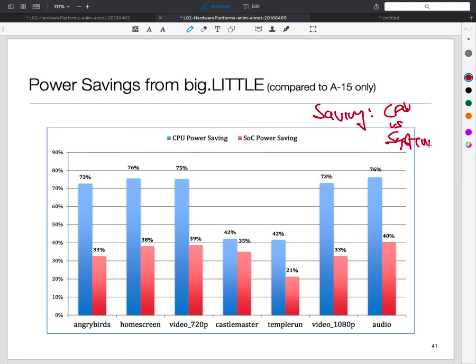Okay, because of color. The GPU, which sits behind the screen to power it up and provide the graphics, so you can have a high performance mode versus low performance. How rapidly you are refreshing it. Okay, so screen is very power hungry. Radios are very power hungry. Writing to flash memory is very power hungry, because when you write to flash memory, it has a characteristic that even if 1 byte is changed, I still have to write a whole bunch of bytes. So flash memory can be very expensive.